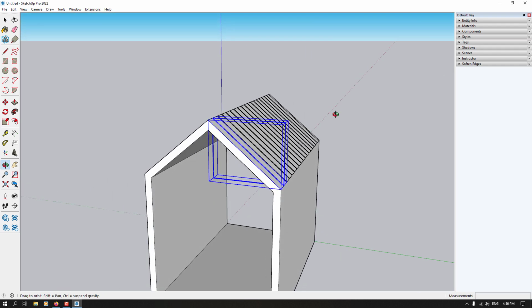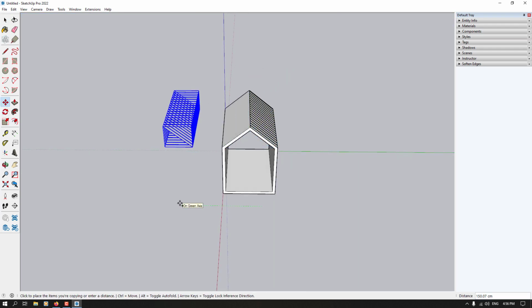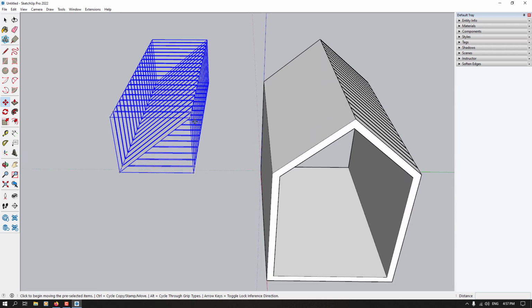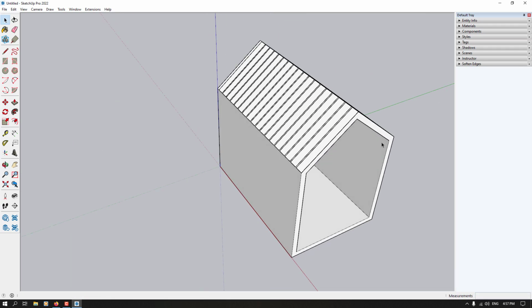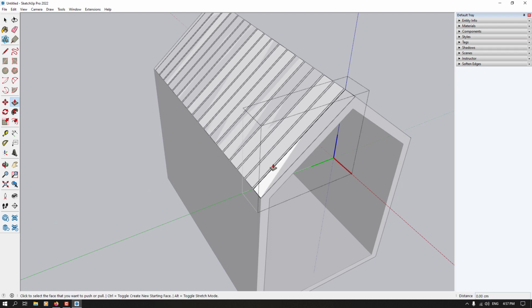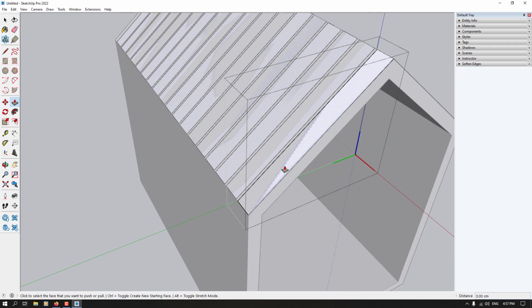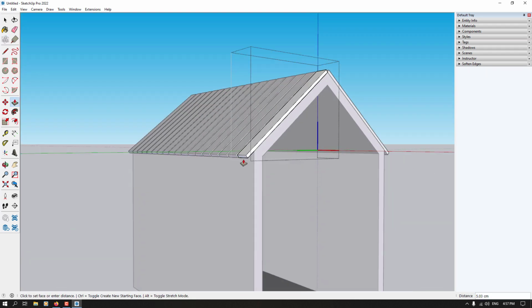Alright, now I want to select all of these components like that, and now I want to make another copy on the green axis. So I'm gonna flip it on the green axis like this and hold this edge to this place. Now I want to extrude all of them at the same time, so I'm gonna click on one of them and use the extrude option about 1 centimeter. Actually wood cuts in the real world have a thickness of about 1.6 centimeters, so I'm going to type 1.6 in here and extrude them something like this about 10 centimeter.